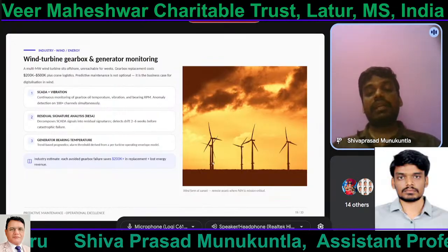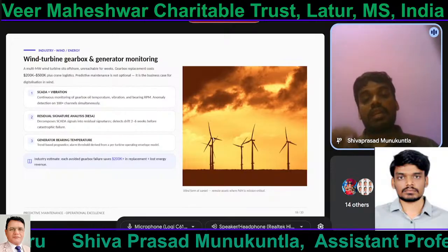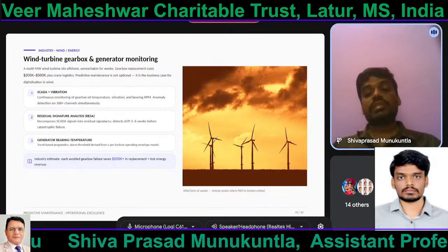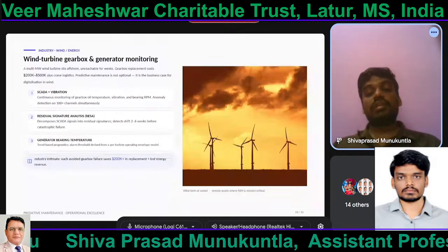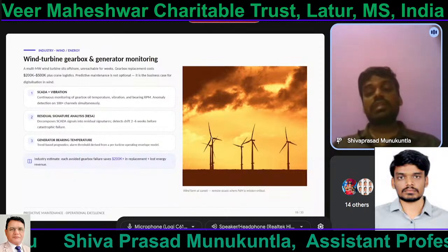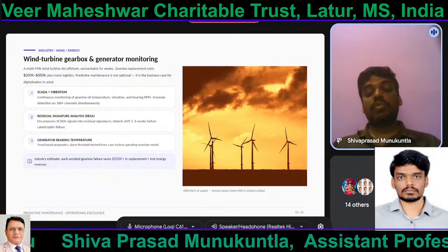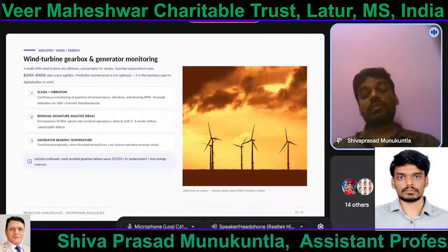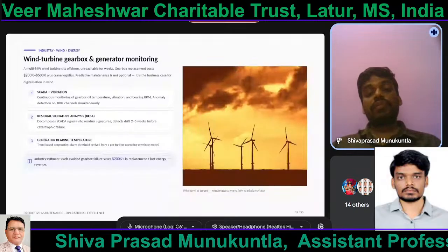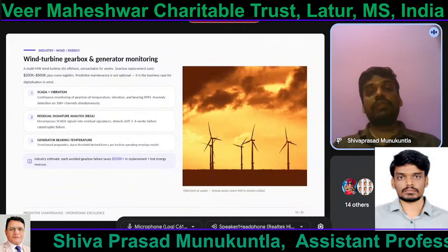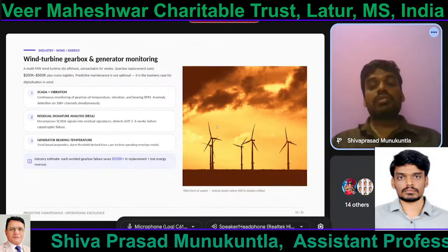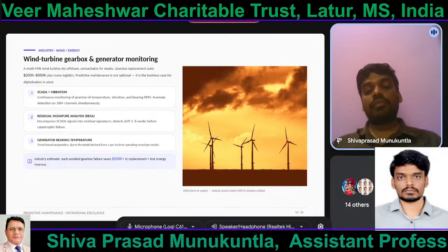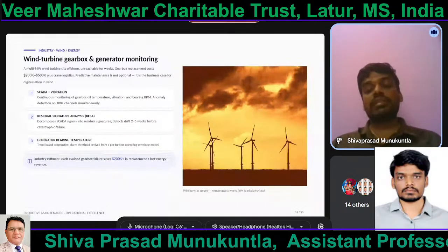But the thing is, the maintenance person cannot go up every day and check whether everything is working correctly. We need to apply oil or grease, or replace motors, and he cannot see that. So they install sensors everywhere, at the motor, the generator, and the gearbox, and they install the models I explained earlier. If anything goes wrong, it will inform them even one or two weeks before. If it breaks down, it may burn or the fans may break, and it will destroy the entire wind turbine.